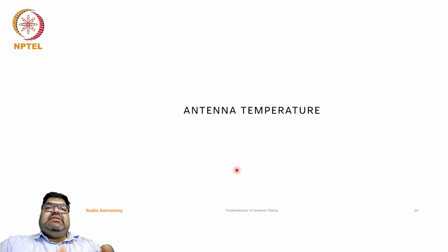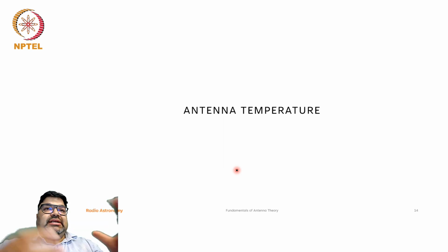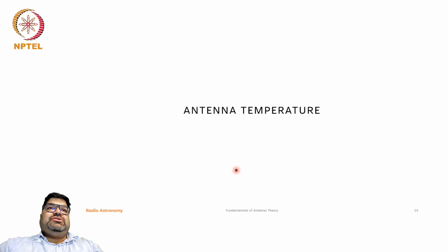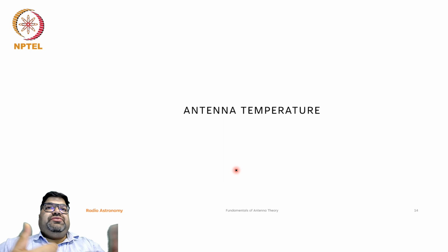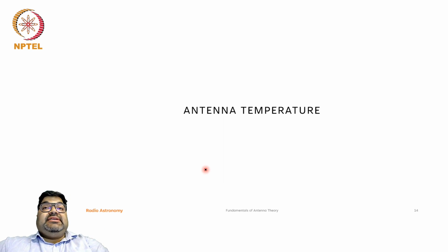And that helps us in characterizing our antenna for radio astronomy in the receiving mode by measuring the radiation pattern of the antenna itself. That is possible just because of this reciprocity theorem, which holds so well. This is a very important concept, and that's why we stress it a little more. It might be a little confusing, but the take-home message should be that antenna properties in the transmit mode are equal to those in the receiving mode, and that's how we are able to do a lot of measurements and characterization of the antenna, particularly in radio astronomy.